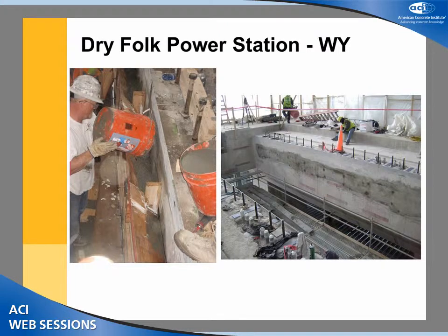And this is the repair area, just to give you some idea what the repair looked like. It was a long beam, about 20 feet long, without any construction joints, anywhere between 2 inches to 12 inches deep, without a single crack. It's a perfect application for an SCC, and the contractor was basically pouring it through a chute.